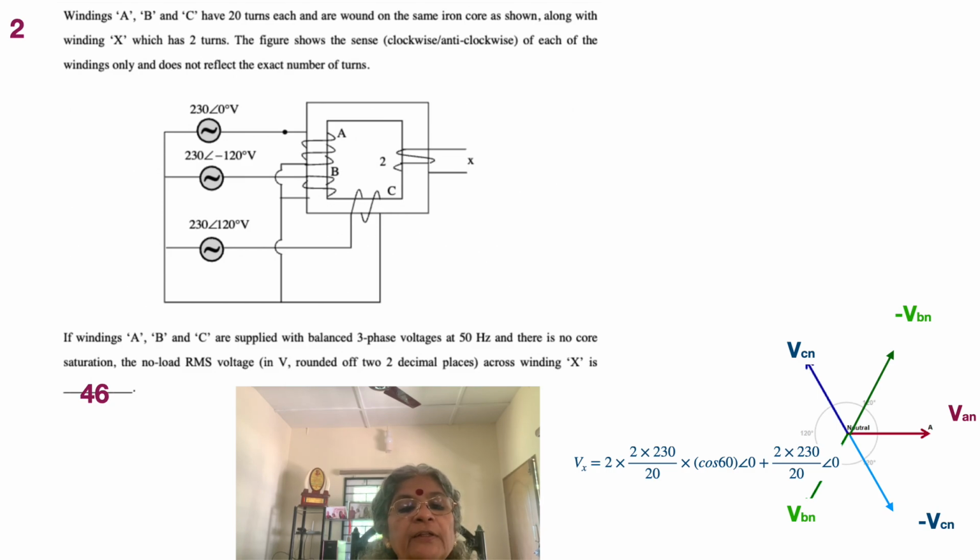If you look at the first coil around the transformer core, we need to find out the directional sense. The coil is going behind and then emerging to the front. Normally you take your right hand and place it such that it follows the current. We can see that the flux is directed downward as far as coil A is concerned. Moving on to coil B, the coil is moving to the front of the core and then going backwards.